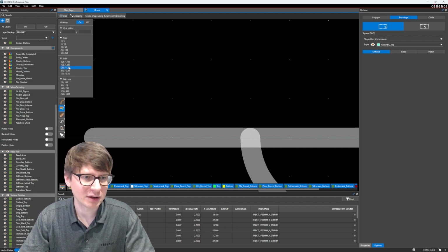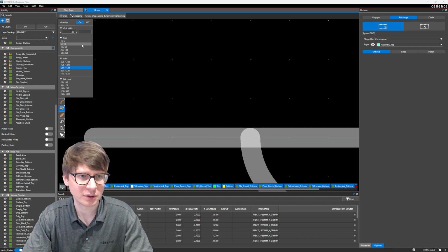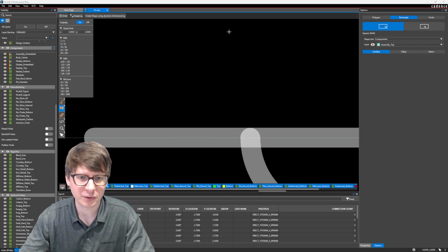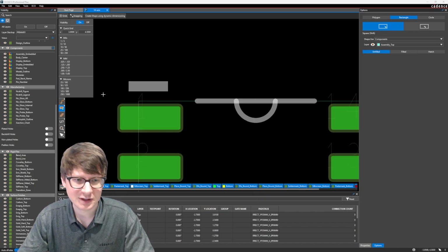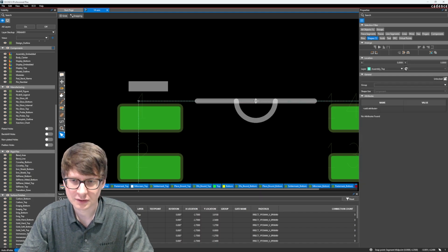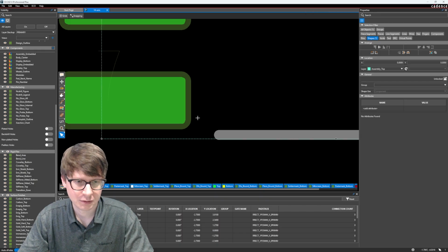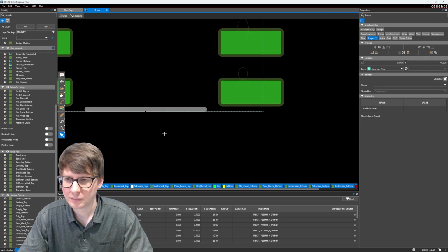But for example, I can go to the grids, set it to in the Y direction to 4.3, oops, sorry, X direction to 3 and Y direction 4.3. And then we can set it to exactly that size. So let's go ahead and do that. There we go.